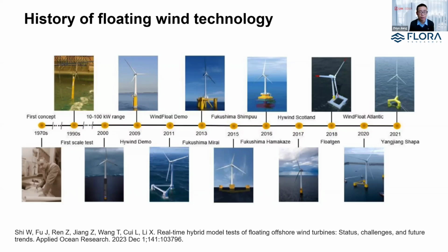As I mentioned earlier, Hywind Demo is a milestone in the history of floating wind. And today we have witnessed many floating wind projects around the world, many in Europe, some in East Asia, and quite a few off the coast of the US and China. There are various types of floating foundations, including spar, semi-submersible, and very few tension leg platforms, which we will come back to later, very briefly. So far, you can see here, semi-submersible foundations with a relatively shallow draft are very popular and dominant for floating wind.